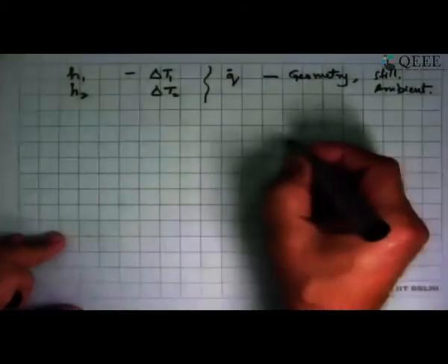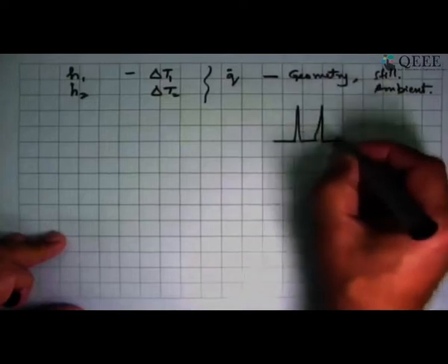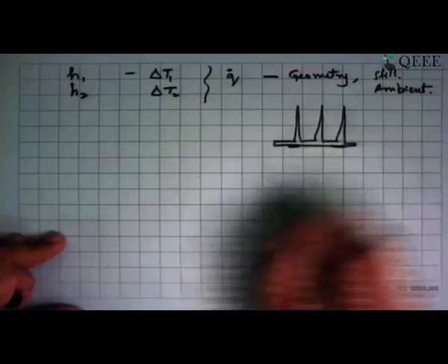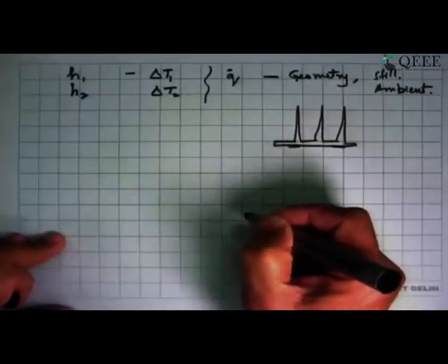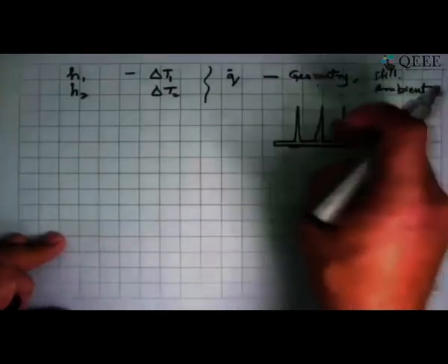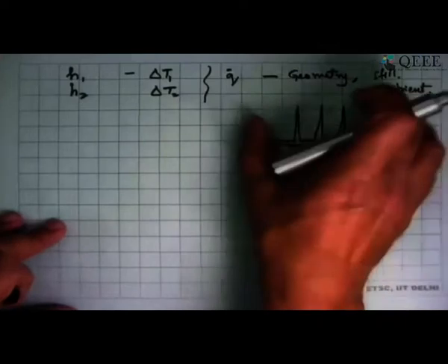Then we say, look, I'm going to change the design of the heat sink, and instead of those things, I will now put thinner ones and put more of these. Or say just put the same thing and make it thinner and longer. So now A has changed, but along with A, something else has also changed, is that the relative configuration of this with respect to the air, the hydrodynamics has changed. So we then say, okay, now let's test this one.